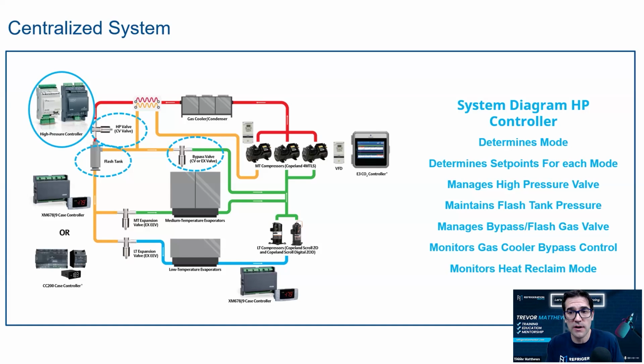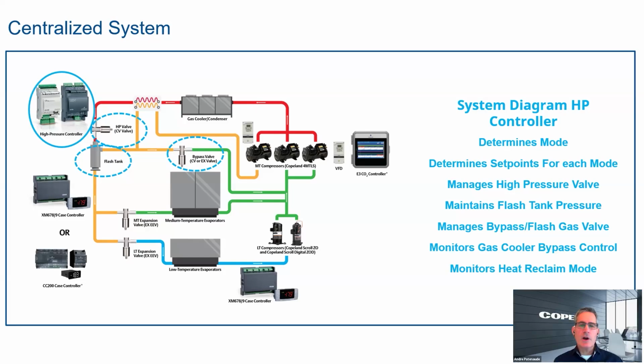And sometimes this takes a while, right? That didn't happen overnight to figure that out. They tried, and their top guys from the company were out there working on that, learning this as it goes. So you've got to spend some time on those trend graphs and learn those. No, you're absolutely right. And you have the flexibility within the E3 to take any graph that you want to look at and layer them one over the other with the exact same timestamp. So you can see a spike here may have been a reaction from this valve not opening or opening too much, and vice versa. So it's really important, once you get to know it, how to use it as a good troubleshooting tool, as you mentioned, Trevor.